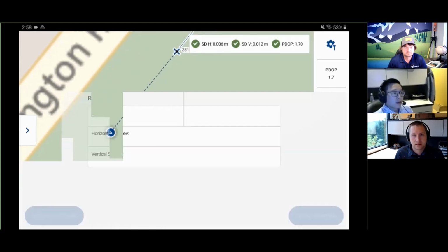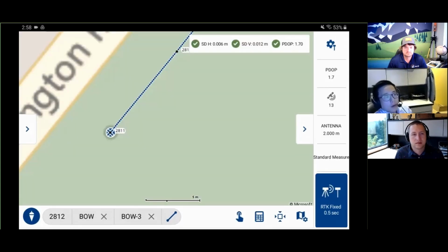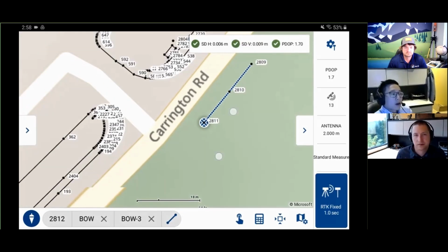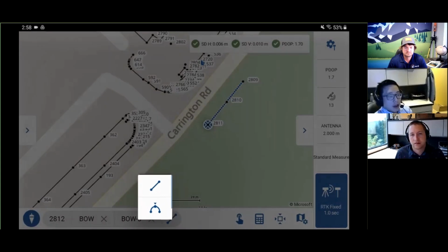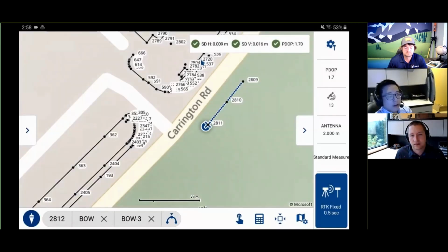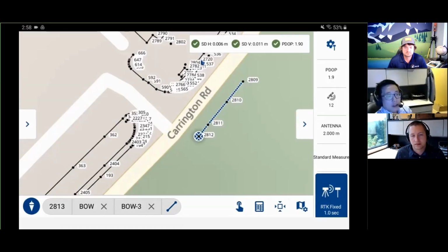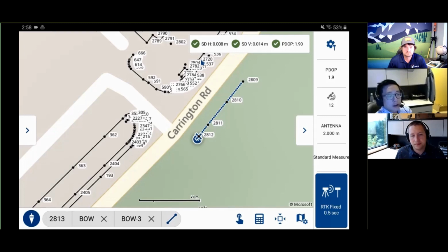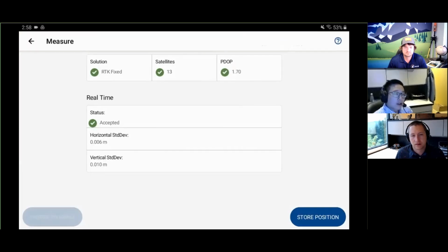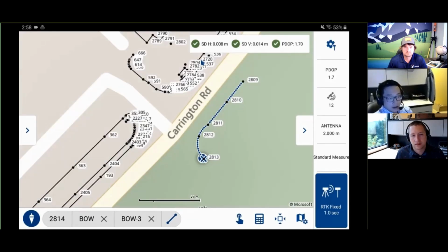I'll just have to update my position on the map there. And then here, if I'm walking up to a curve, I'll select on that to toggle on that I am walking to the middle of a curve there, and I'll take that shot, and then you'll see it automatically updates back to a straight line segment, and then it'll prompt me to walk to the end of that curve, and then you'll see the construction line update to show that arc.